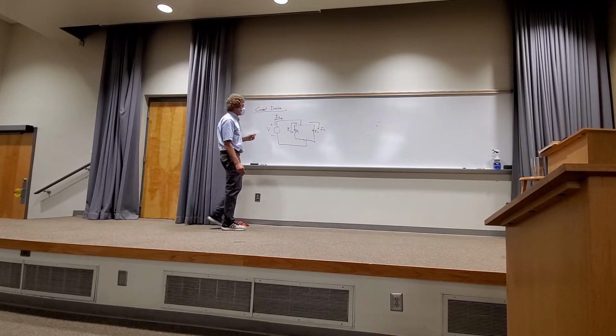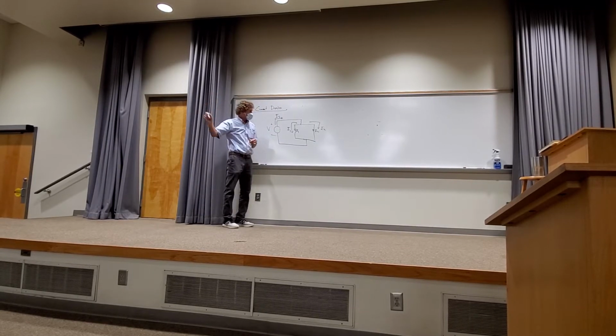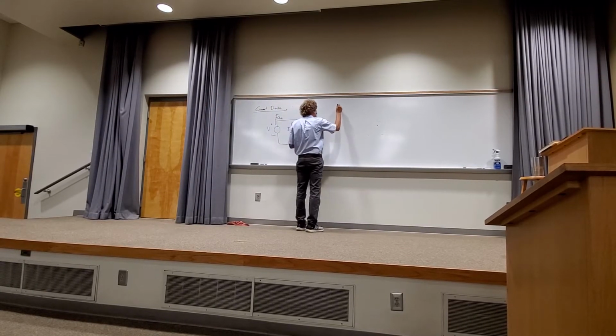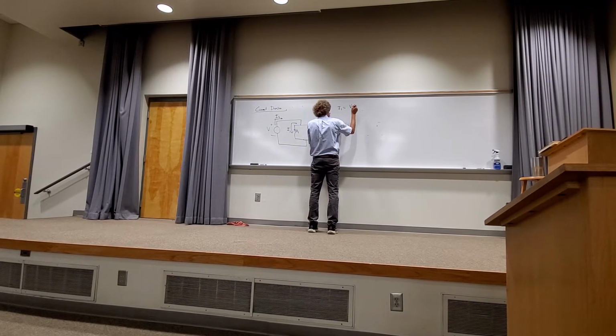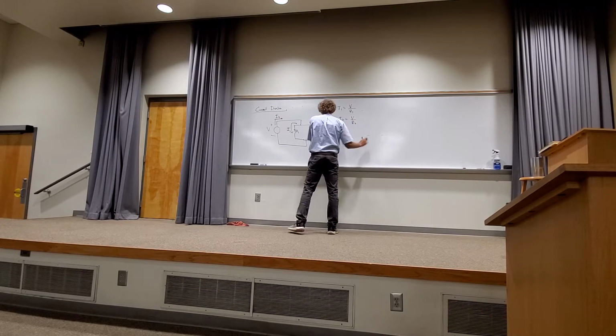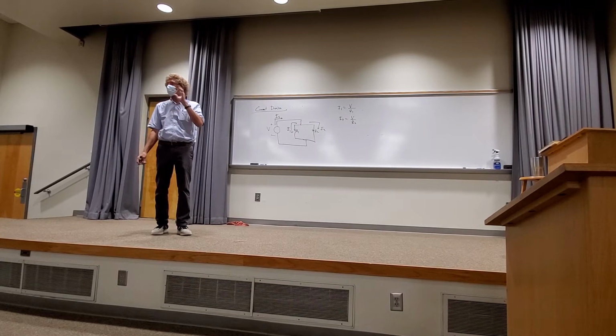So, how many see that these two resistors are in parallel? How many see the voltage across them is V? Right? And therefore, I1 would be equal to just V over R1. And I2 would be equal to V over R2, right? Y'all agree with that? And can y'all hear me okay? Yes. If you can't in the back, I will wear a mic, I'll do whatever I need to. Y'all with me on this one?